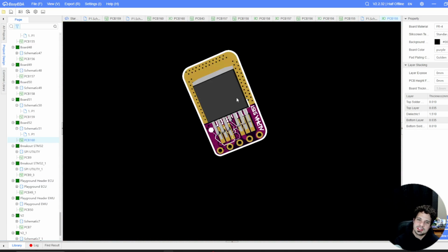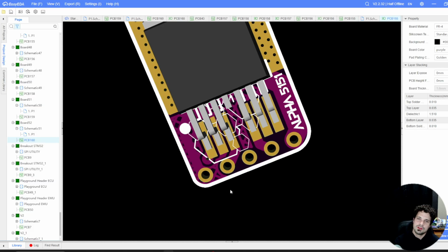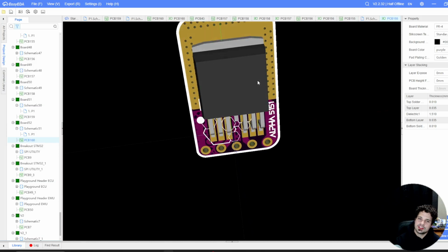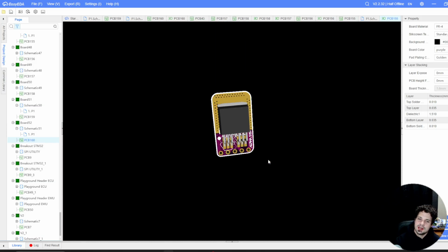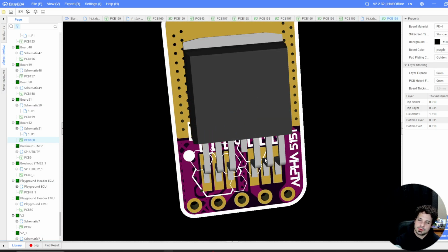And this IC right here uses 12 volts in. It uses 12 volts out to the VTEC solenoid. It uses a ground input as well as a control logic level from the ECU, so an on and off signal. And the one additional thing that you're going to find on these 5151 chips is there is a diagnostic pin, which is an open drain pin, meaning that it is held low or held at a 0 or ground reference.